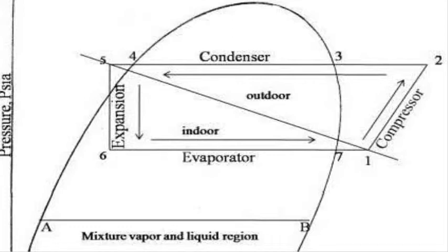The air conditioner condenser, located between points 2 and 5, is a heat exchanger. It rejects both the sensible and latent heat absorbed by the indoor evaporator plus the heat of compression from the compressor. There are 3 important states that take place in the condenser heat rejection. The first state, points 2 and 3, is superheat, where it rejects hot superheated vapor. It removes sensible heat. At points 3 and 4, it rejects the saturated vapor's heat and starts changing phase from vapor to liquid.